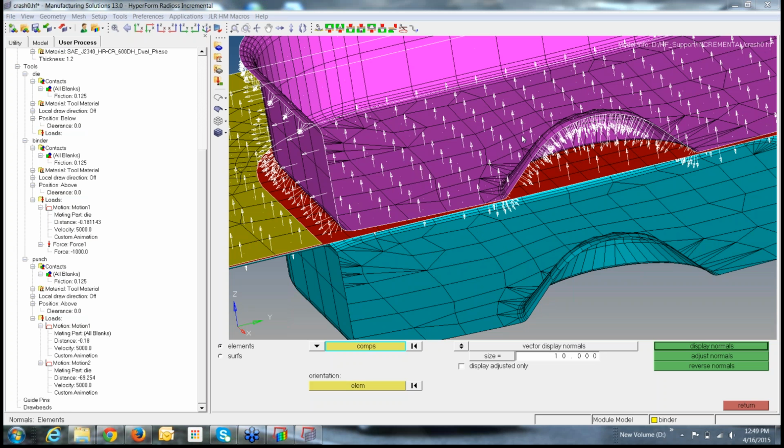It will only be generating 20 animation files. With more, it will run for a slightly longer time, so set the count to 20. For regular forming simulation, an animation count of 10 should be more than sufficient. If you have multiple other tools, side cam tools, then it makes sense to add more animation count.